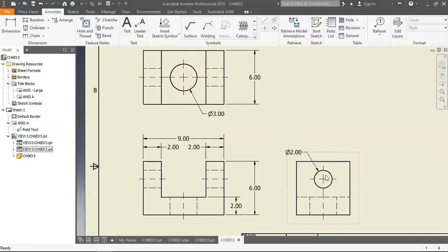Remember, you need 3 dimensions per circle. So I'm going to say from the edge to right here, you can do it that way. You can say from the bottom to here. Oh, I guess it didn't work. Hit escape, try it again. Is 4. And I'm going to go from here to here is 3. And then I'm just going to clean that up because now it's kind of in the way. Nope, I don't like that. There we go. That's a little bit better.